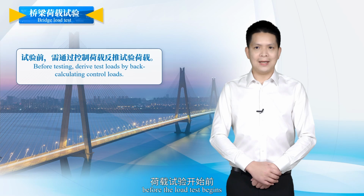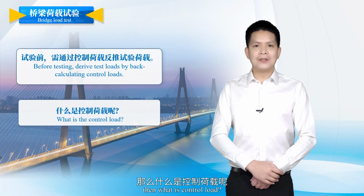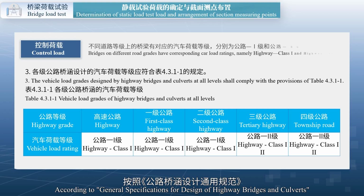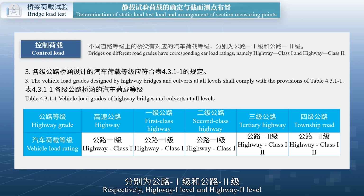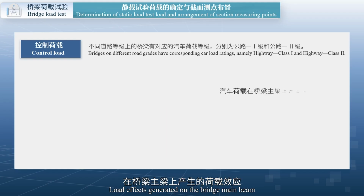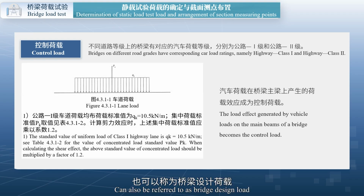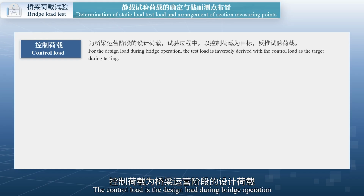Before the load test begins, it is necessary to deduce the test load from the control load. Then, what is control load? According to general specifications for design of highway bridges and culverts, bridges on different road grades have corresponding vehicle load ratings, respectively highway I level and highway II level. Different load ratings of vehicle loads generate load effects on the bridge main beam, becoming the control load, which can also be referred to as bridge design load. The control load is the design load during bridge operation.